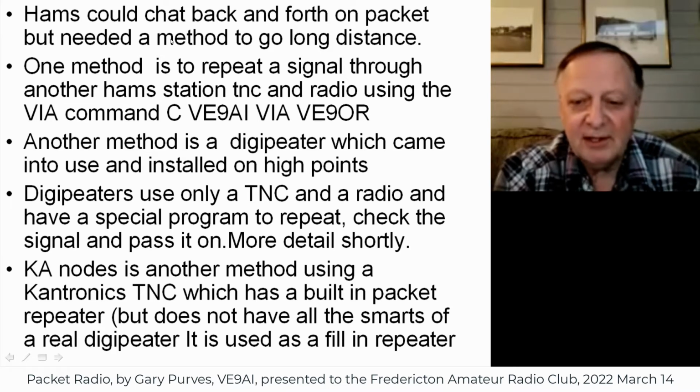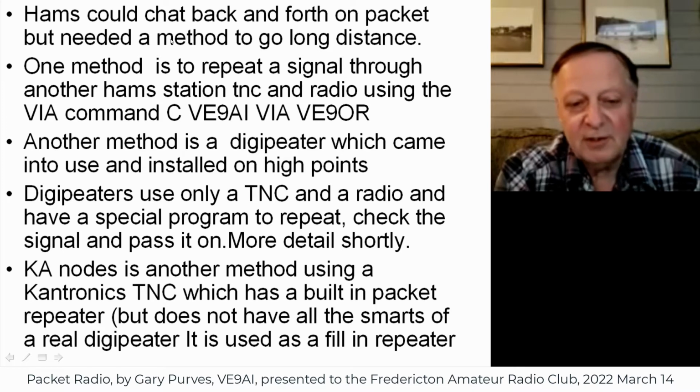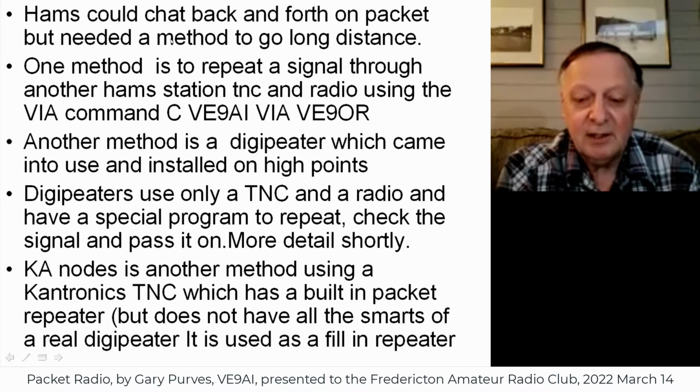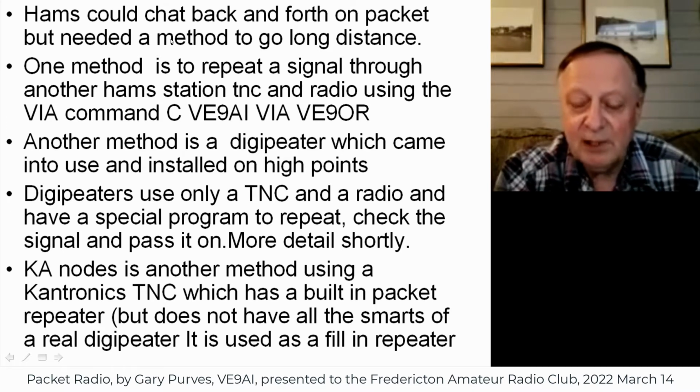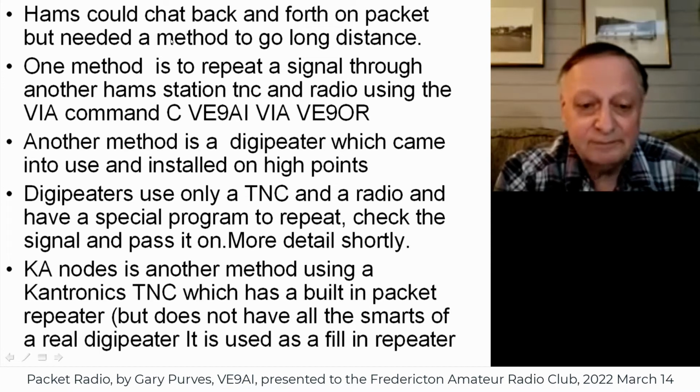KA-Nodes is another method, using a Kantronics TNC, which has a built-in packet repeater. It doesn't have all the smarts of a real Digipeater, but it's used as a fill-in repeater. I'm running one here right now at my place, for anybody in town who couldn't get to the nearest Digipeaters.